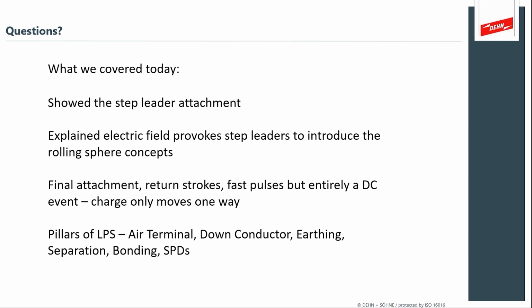Sure. The spacing of the air terminals: if they're particularly close together, you might infer that it was a severe standard that they were trying to meet. If it looks like a mesh, and the mesh is very tight, that's a more severe adherence to the standard. So there might be ways to back into what the designer's thought process was.